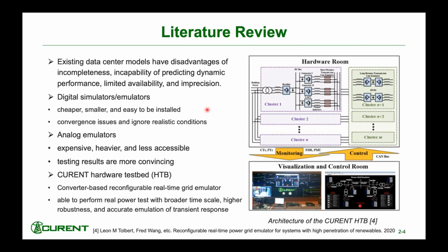However, they usually suffer from instability or convergence issues, and often they ignore realistic conditions like the control bandwidth, the communication time delay, or the switch noise. While the analog-based emulators are more expensive, heavier, and less accessible, the testing results are more convincing and are usually preferred by engineers.